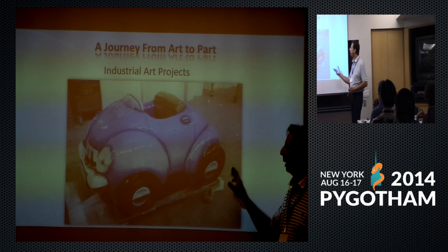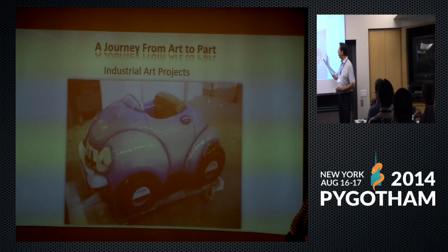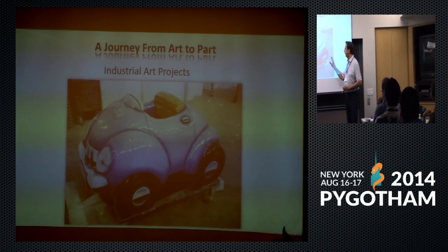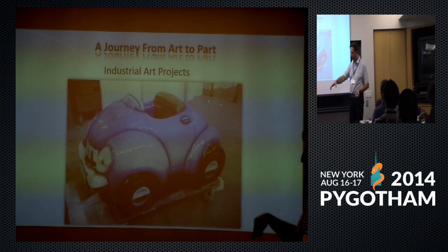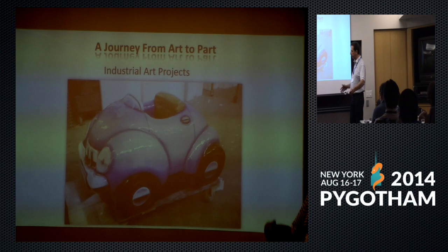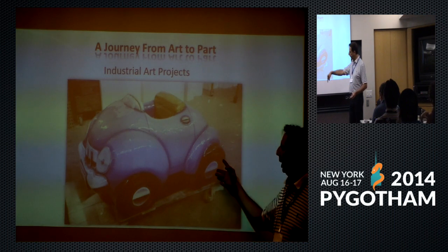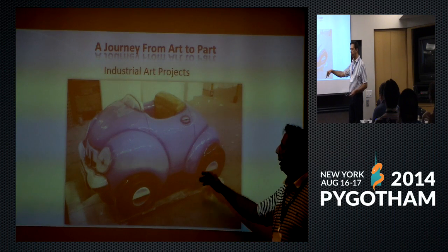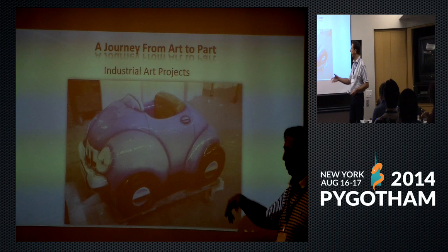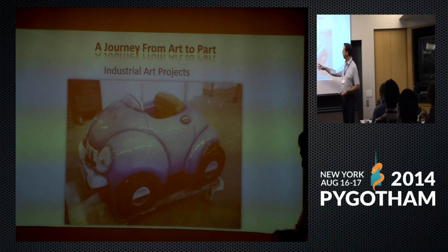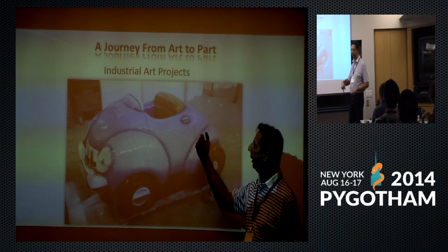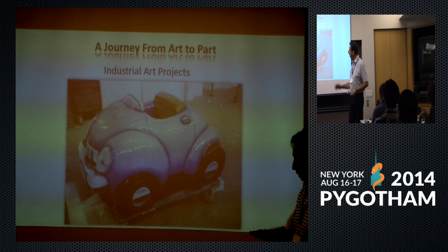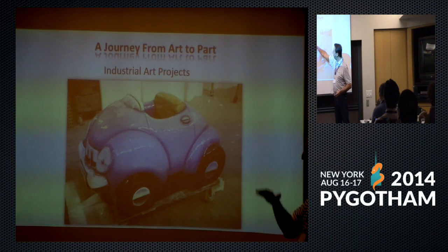The way it's produced is we use a 3D CNC router, which is pretty much like that plotter example. I said we put a big foam block in, and then a cutting tool basically skims the surface and carves the shape of this car into it. You know, when you take a look at an orthographic view, which means straight view, you could not reach the inside of the car.